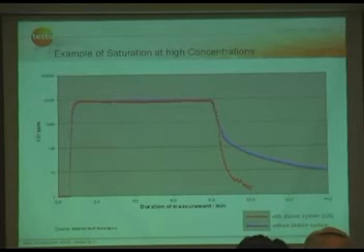That means you have to rinse and rinse and rinse the analyzer just to make sure that the CO concentration gets out of the sensor. And because of the dilution system, you will get the high reading as well. But since the sensor only gets the very low concentration, it's very fast to get to 0 again.